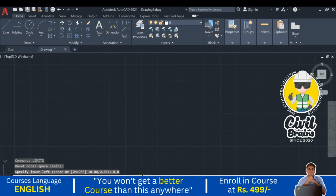This is the dimension of the A3 paper in mm. Here it is already showing 42 by 29.7 in centimeters. If you give centimeters and then draw in mm, it will get confused, because we have set the units in mm. So always give this in mm, and press enter.